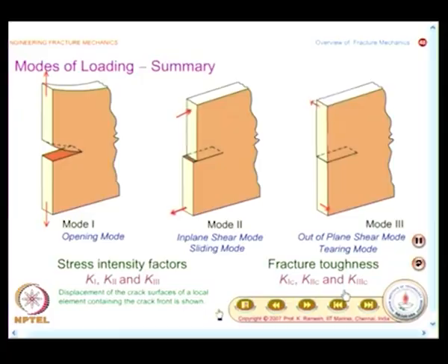And I had already noted, in the case of simple strength of materials, what did you do? When you had combined loading, you invented the concept of principal stresses and you utilized the result from a simple tension test of the yield strength, and you find out how the failure will occur in combined loading. You do only one test.